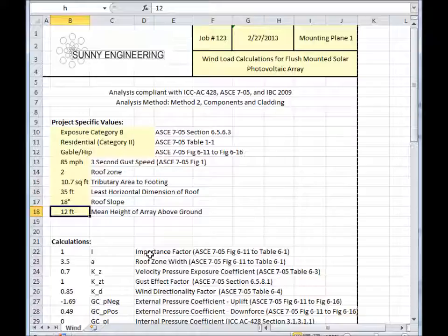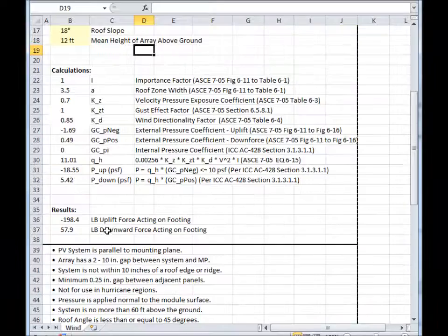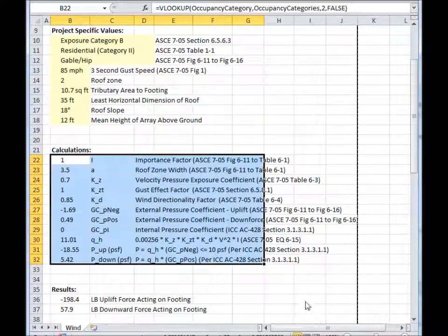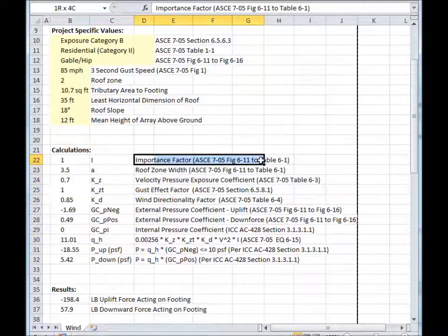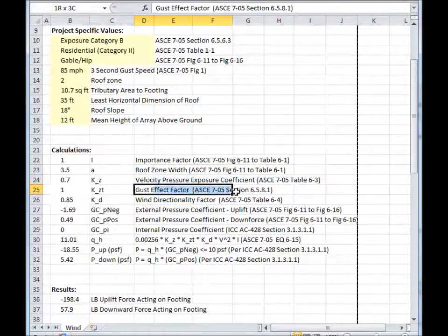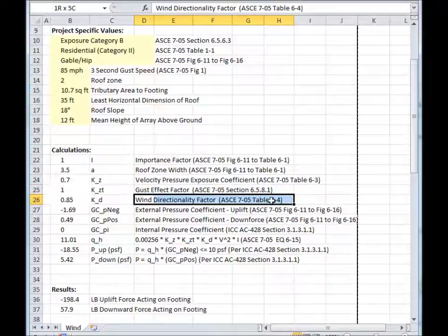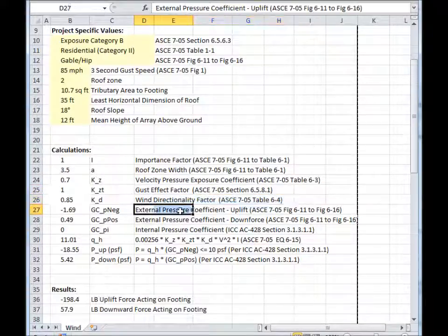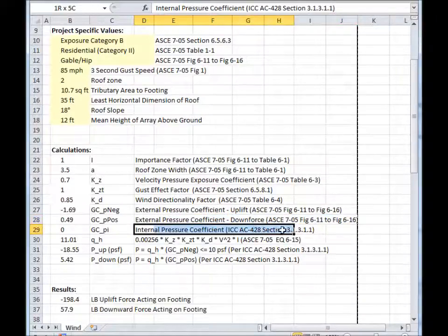If you've got a 1-story building, this is frequently going to be between 10 and 14 feet, depending on how much attic space you have, but if you have multi-story structures, it'll go up from there. If you want to follow along with these calculations in the ASCE 7, I've included references for everything that was done here, so it should be really easy to follow along and verify that they're working correctly. And I can't promise that they are working correctly, so you should definitely double check.